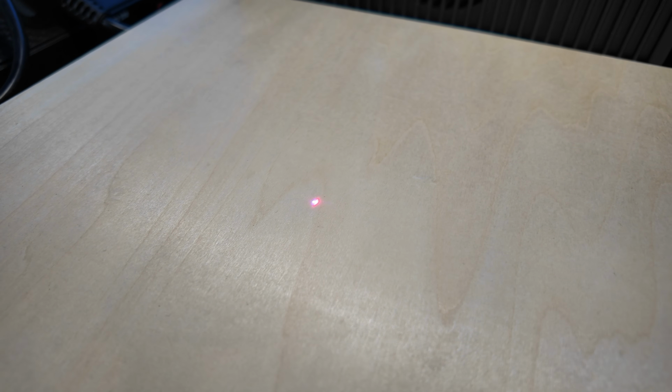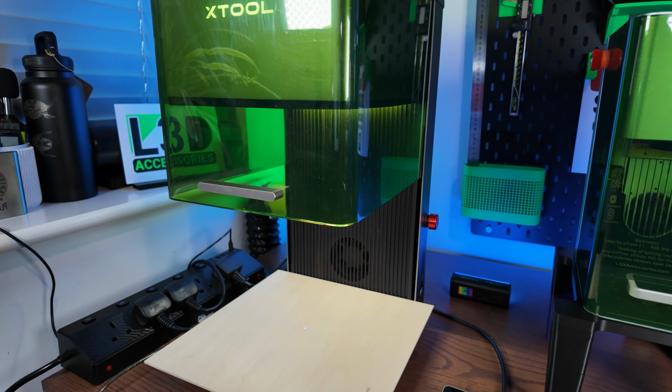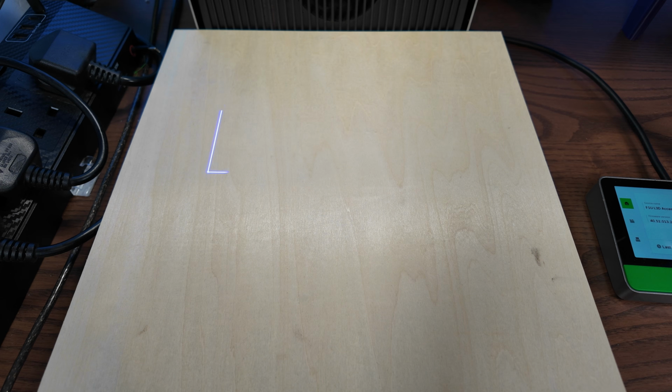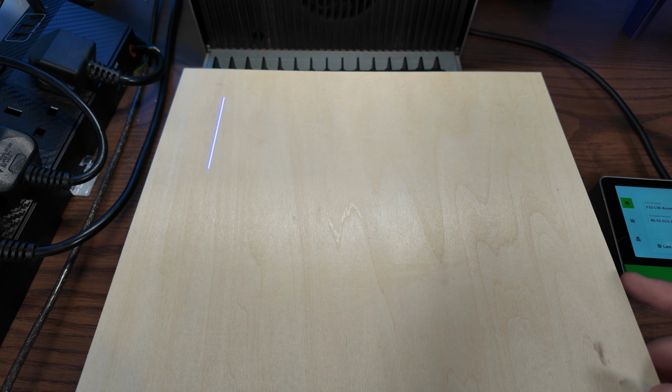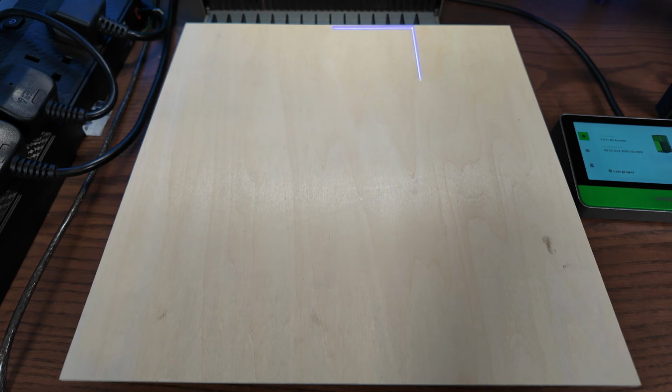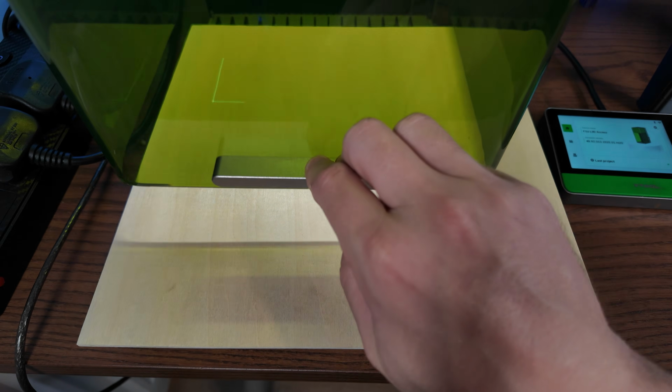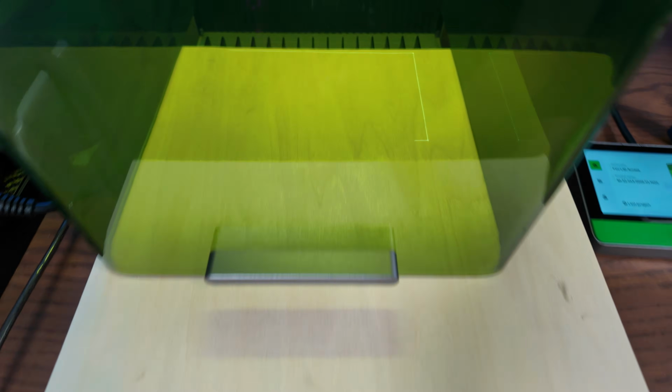You'll also see I'm not focused, so I'm going to adjust the laser height to join the dots. And that is now a focused laser ready to engrave. The next thing we're going to do is frame the actual engraving area itself to make sure we're happy with where it's going. There you go. That should allow me to ultimately save a lot of the material space, because that's what we're doing with smart nesting. We're trying to optimize this, but also I'm going to have lots left over at the end. So there you go. We've got our laser central.